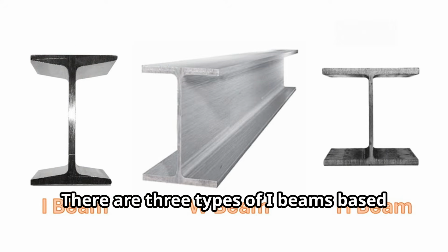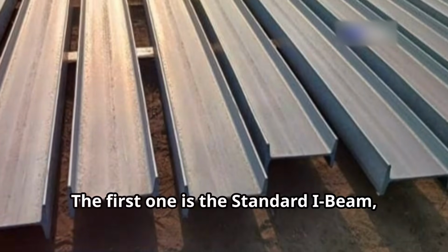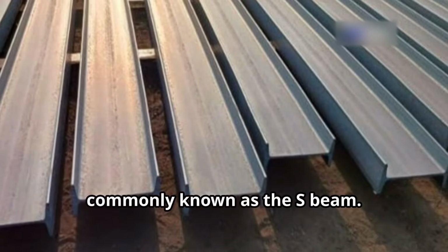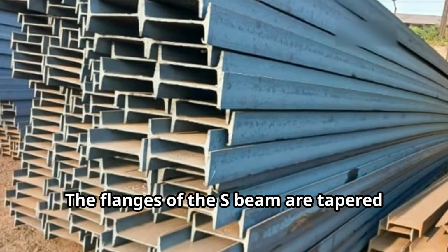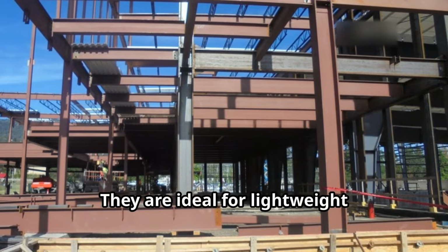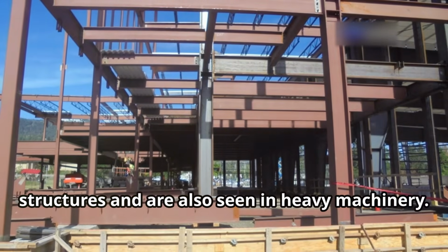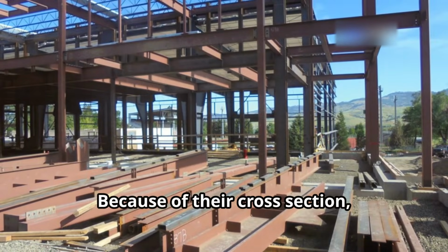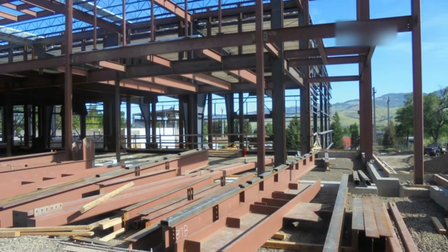There are three types of I-beams based on their cross-sections. The first one is the standard I-beam, commonly known as the S-beam. The flanges of the S-beam are tapered and get thinner further from the web. They are ideal for lightweight applications like roofs and smaller structures and are also seen in heavy machinery. Because of their cross-section, they are best suited for supporting loads acting normally on the flanges.